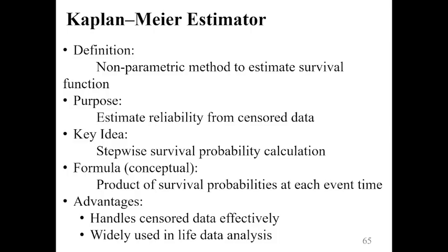One of the key strengths of the Kaplan-Meier method is its ability to handle censored data effectively, which makes it highly practical for real-world reliability analysis where not all units fail during the observation period.